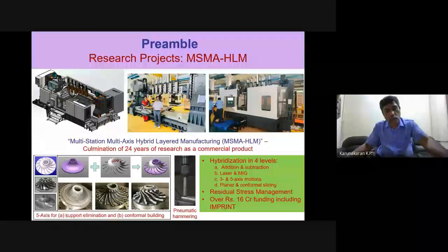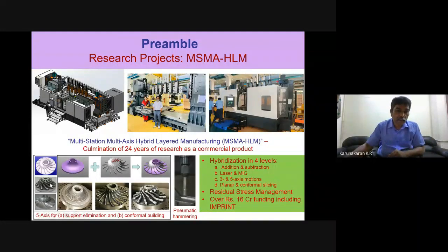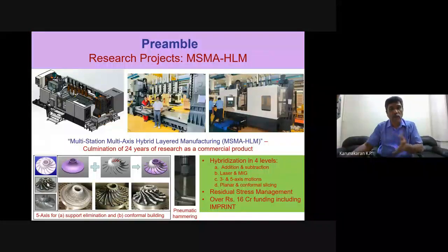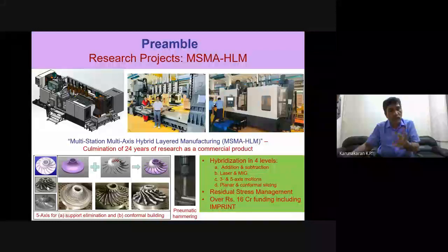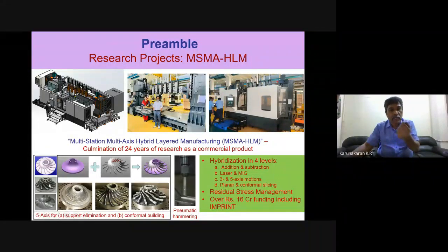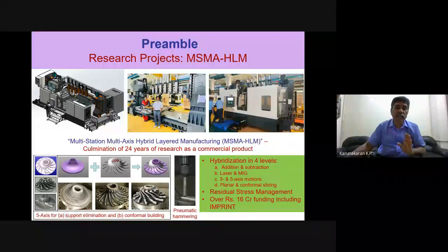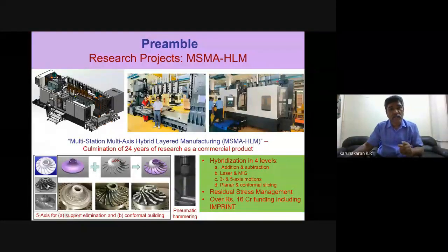So here in this particular part, we grew in horizontal layers. But then you see that in all additive manufacturing, you need some kind of support mechanism to take care of the undercut or overhanging features. You see the impeller, it is a highly twisted blade. What we drop are molten droplets, so the droplets have to be captured in the appropriate place. That is why we have the rotary table here. We rotate the B and C axis appropriately with appropriate XYZ motion so that the right place receives the droplet. We have developed our own software for doing this. So in this particular case, the left 3 figures, it is horizontal growth in horizontal layers, but 5-axis motion is used to alleviate the need for support structures.